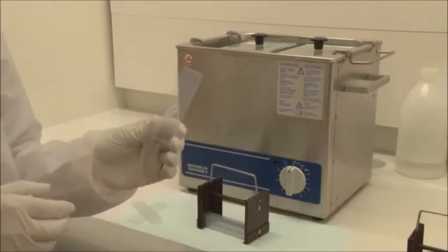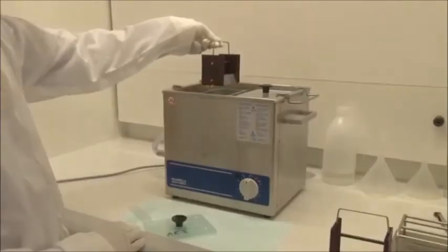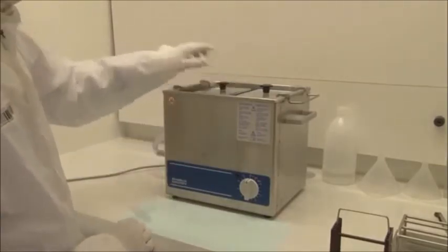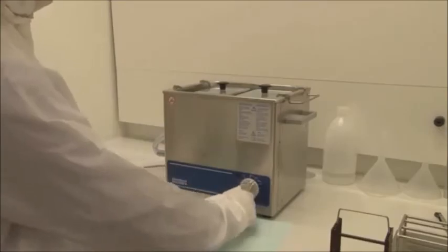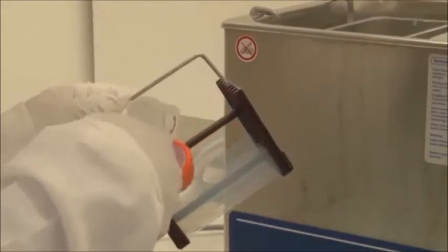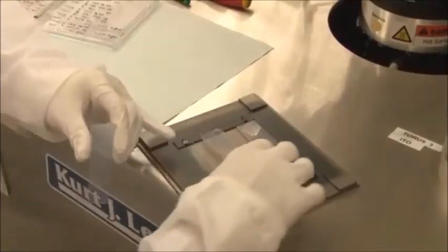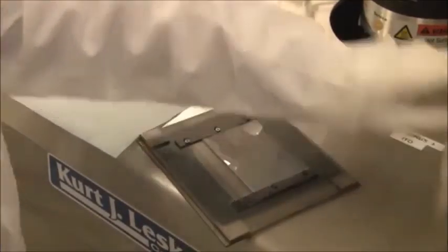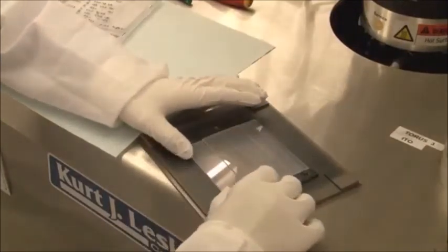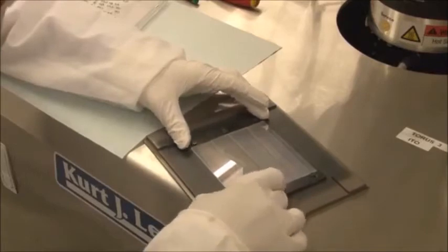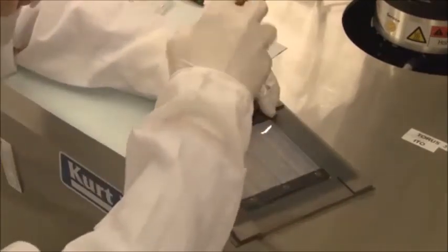Before deposition, the samples have to be cleaned in a so-called ultrasonic cleaning bath. The potential dirt and dust particles are removed. Since the solar cell device is only several hundreds of nanometers up to a few microns thick, a dust particle on the substrate will generate a shunt between the front and back contact in the final solar cell. Here we use a substrate that is coming from the Japanese Asahi Glass company and already has a TCO coating on it. The TCO coating is a fluorine doped tin oxide and is responsible for the hazy color.